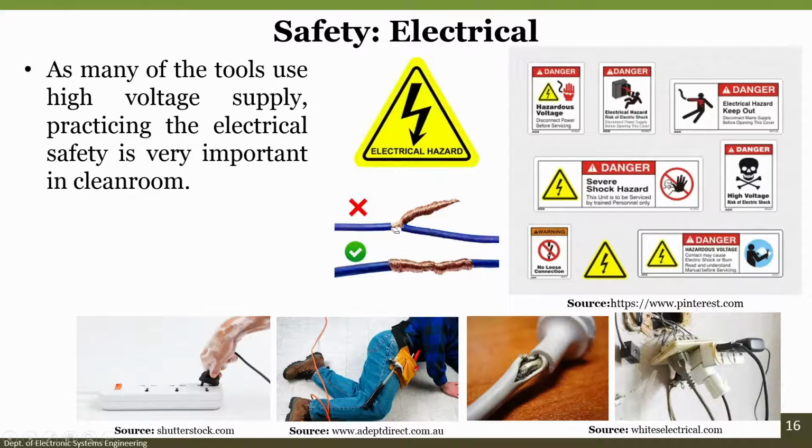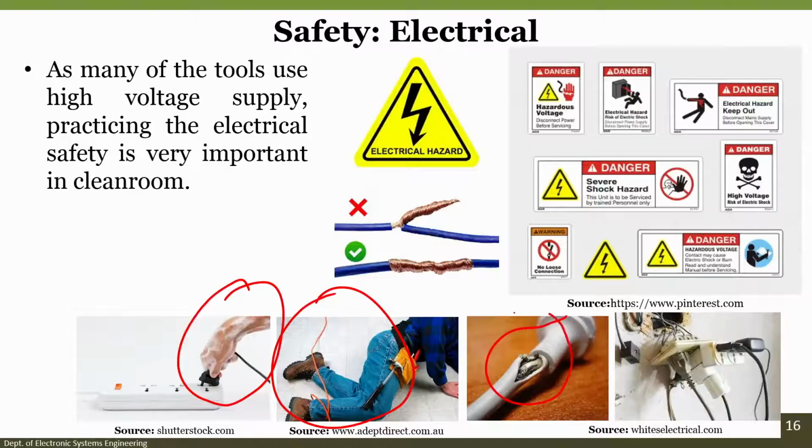Don't use wet hands and connect your system. You should not work in an environment where there is tangling of wires around your legs. You see, this is a broken cord. You should never use a broken cord. This is not allowed at all, right? It can cause a tremendous amount of fire and short circuit. This is not allowed. Okay.